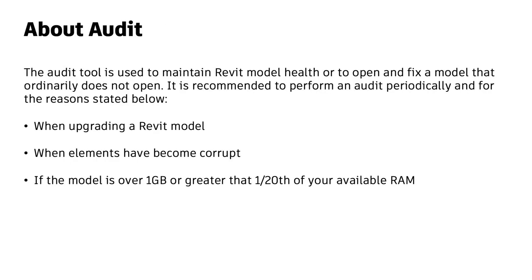The audit tool is used to maintain Revit model health or to open and fix a model that ordinarily does not open. It is recommended to perform an audit periodically and for the reasons stated below: when upgrading a Revit model, when elements have become corrupt, or if the model is over 1 GB or greater than 1/20th of your available RAM.